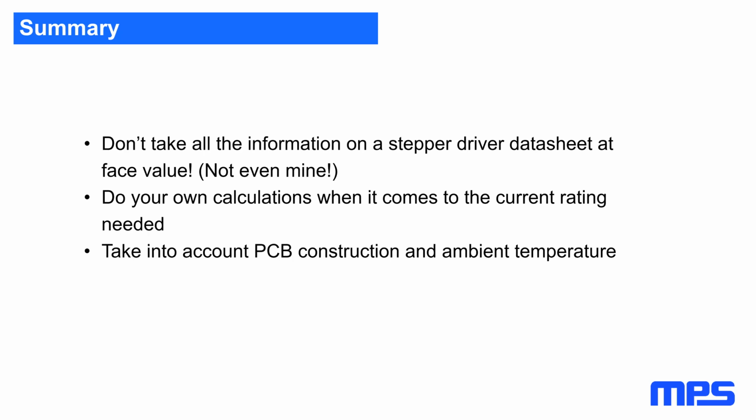So to determine the suitability of a given driver for your application, you have to do your own calculations using parameters like the on resistance of the output stage and thermal characteristics of the IC package. This, in combination with PCB construction, copper area, and ambient temperature requirements, will determine if a given part will work for your application.